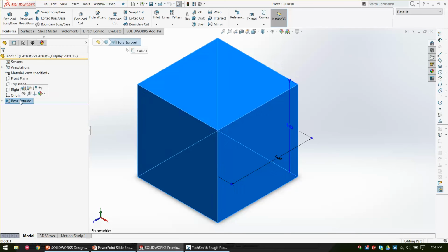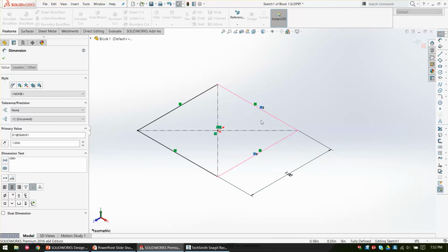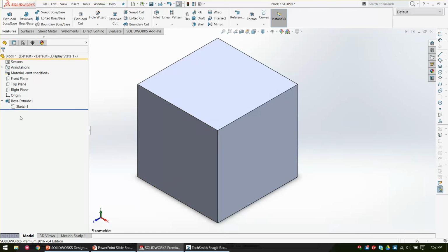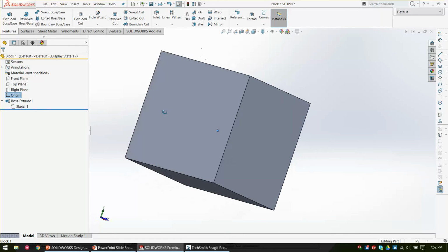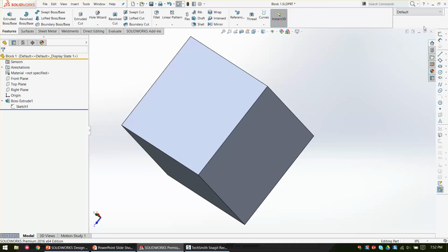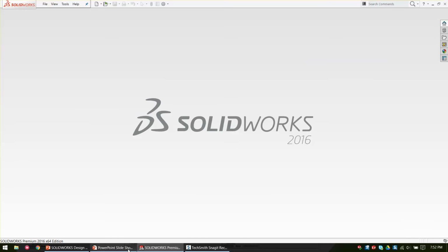And I think our typical extrude. And even on this typical extrude, we want center origin, single dimension, and equal on our 2 sides, and then an extrude mid-plane to give us a center origin to our geometry. So even in a simple block, you can put in a significant amount of design intent based on what it is that you're trying to accomplish.